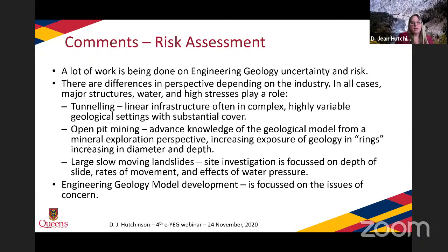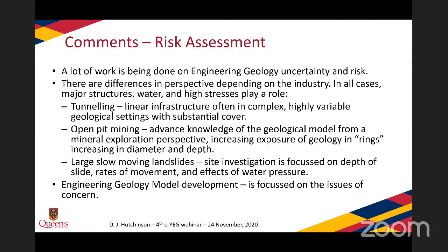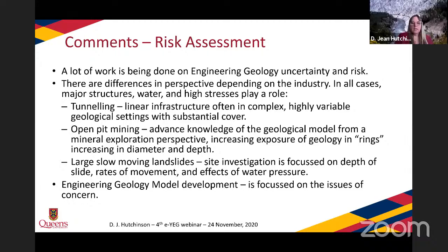And then there are large, slow moving landslides that I talked about very briefly in this talk. In this case, the site investigation you do is focused on assessing the depth of the slide, the rates of movement associated with different shear zones, and the effects of water pressure. In cases where drainage is installed into the landslide, there's also the follow-up to understand how that water pressure change, to do with inputs from climate and outputs with drainage, affects the movement and the risk. And the engineering geology model development in each of these cases is really focused on the issues of concern.